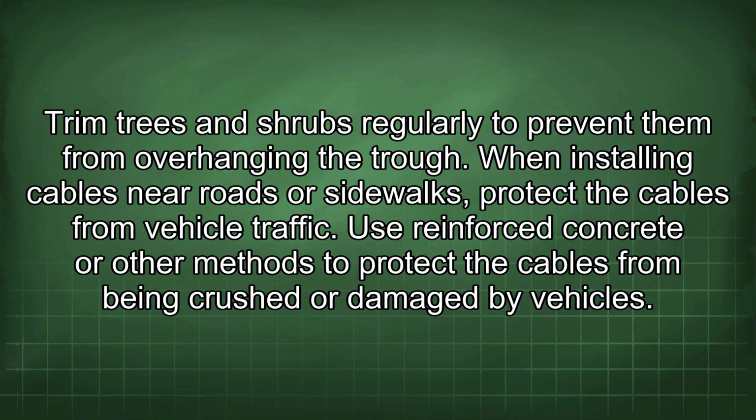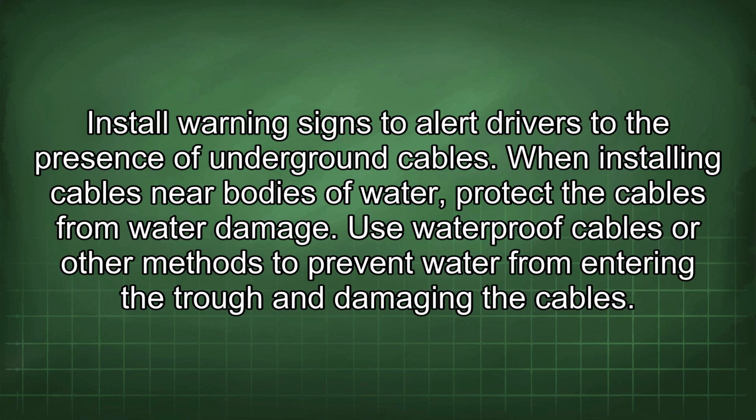When installing cables near roads or sidewalks, protect the cables from vehicle traffic. Use reinforced concrete or other methods to protect the cables from being crushed or damaged by vehicles. Install warning signs to alert drivers to the presence of underground cables.